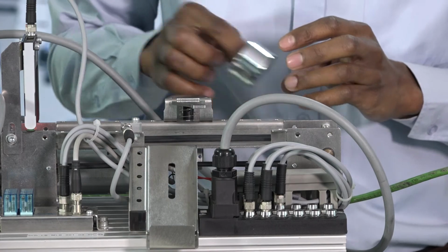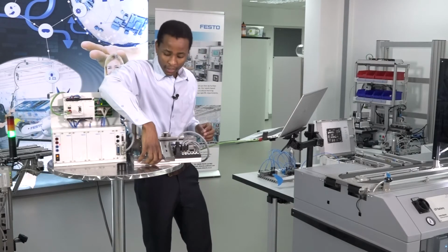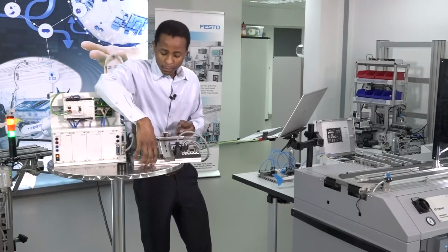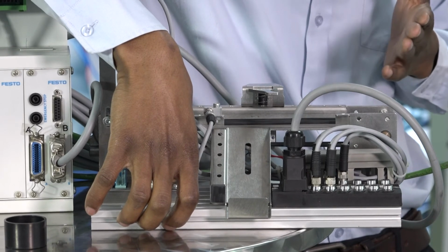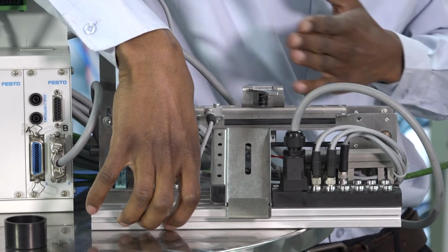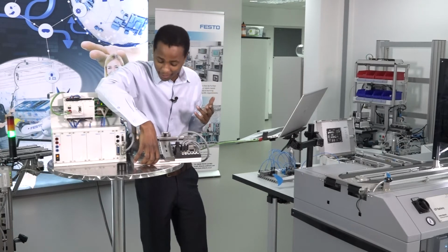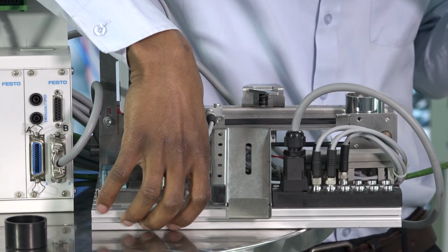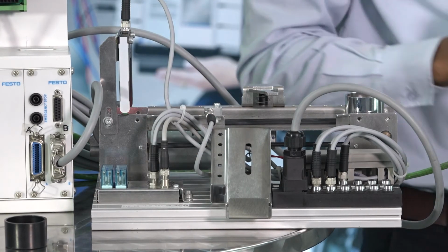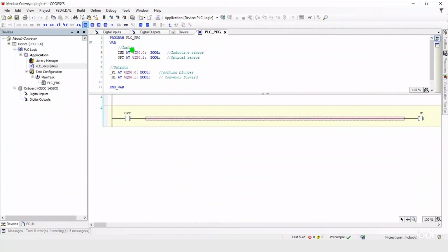And by just looking at it, we can actually check by using this manual override here. We need to sort of time it to be able to determine how much time the conveyor needs to transport a part from the start to the end. So I'm going to start in my head the timing. So we have 1, 2, 3, 4, about 4 seconds. Just to be on the safe side, we'll make it 5 seconds. So we add a function block in between the input and the output.